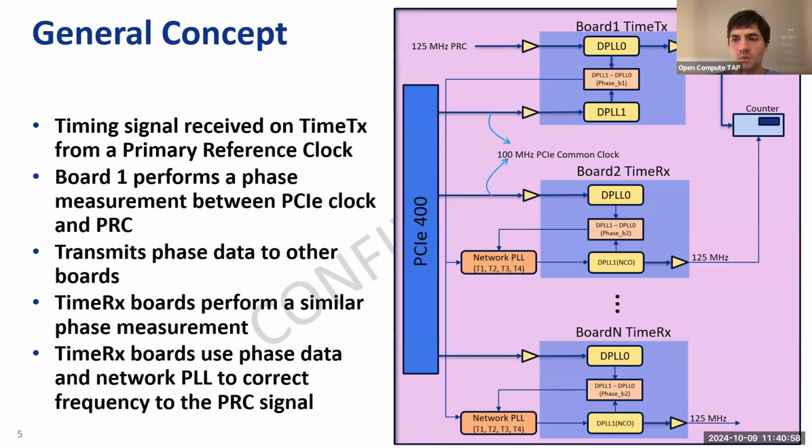Yes. So, a question for you, Simon. The element that you have on the right side, here, the counter. I'm assuming that is an off-the-shelf counter. You're measuring basically the difference between frequencies. That needs to be part of the system. What is the minimum you can do? Can you just use a mixer and do things in the frequency domain, a mixer with a low pass, and then look at the component that you get between the two? Is that correct?